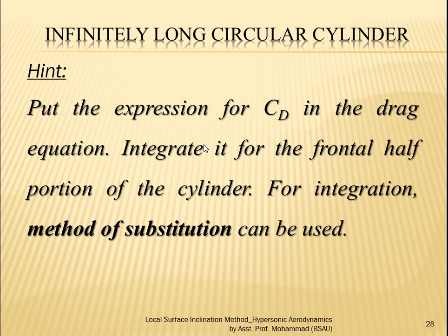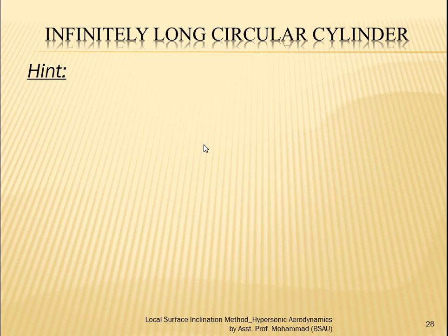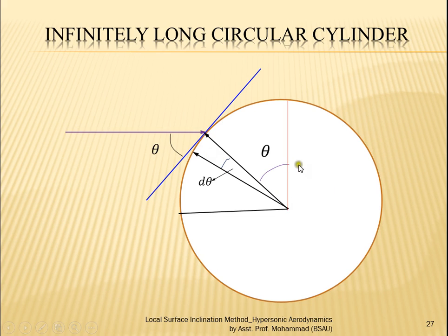This elemental area, the Cp, and the dynamic pressure q infinity, all three together give the elemental drag, dD. And then for finding the complete D, we have to integrate with respect to theta from 0 to pi.